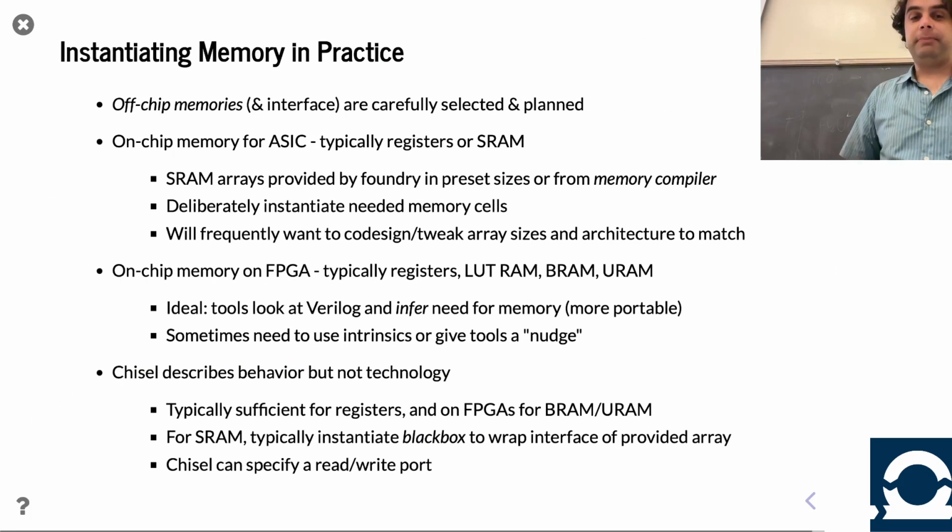So when it comes time to actually choose memories in your architectural design, what can you do? Off-chip memories, like I said, you're going to really plan those out. It's not something you change late. You're going to know from your early modeling, as well as you start building it, what your cost targets and performance targets are. There are so many pins involved, and it involves so much in packaging and entire system design, that it is hard to change those things late. So if using HBM, it's a very different experience than using, let's say, LPDDR or DDR. That's a huge change to the rest of the system.